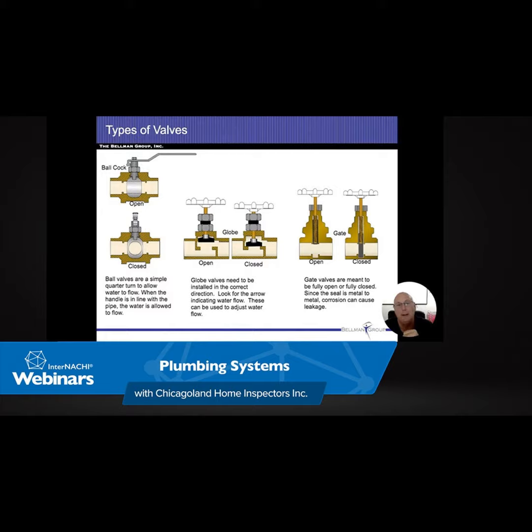Most temperature pressure relief valves for water heaters are set at 210 degrees, so we would never get to that boiling point. The pressure side, which is that spring loaded poppet valve, is going to open up at 150 psi for a water heater. They do have smaller ones that open up at lower pressures, but typically those are for hydronic systems or steam systems. Water heaters are 150 psi. I do want you to remember that number.